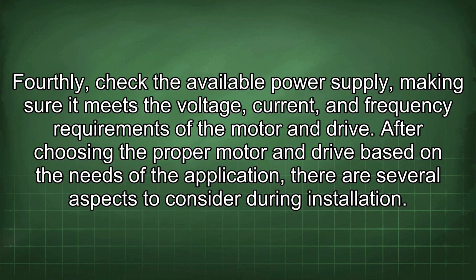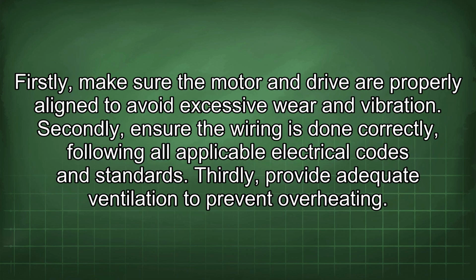Fourthly, check the available power supply, making sure it meets the voltage, current, and frequency requirements of the motor and drive. After choosing the proper motor and drive based on the needs of the application, there are several aspects to consider during installation. Firstly, make sure the motor and drive are properly aligned to avoid excessive wear and vibration.